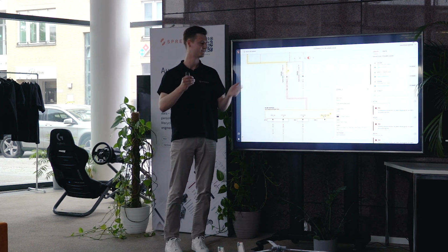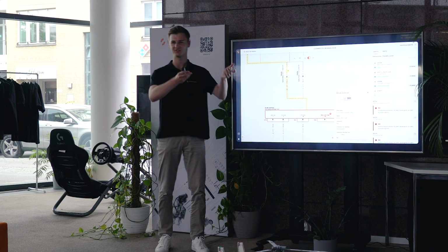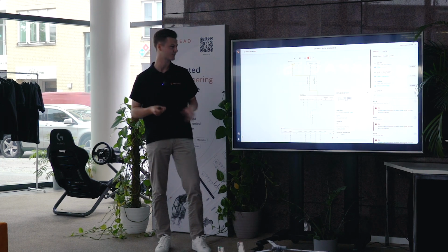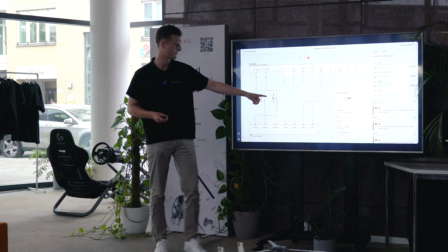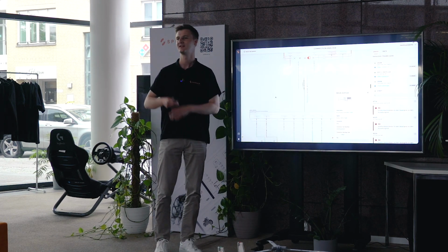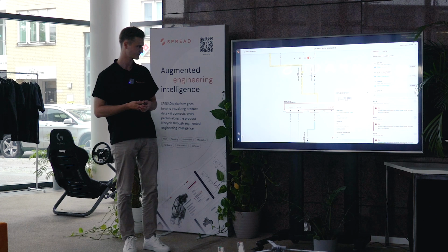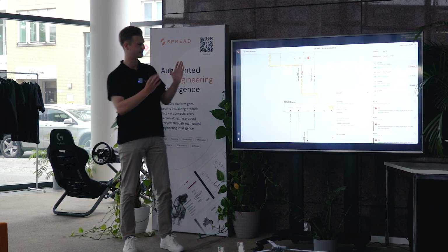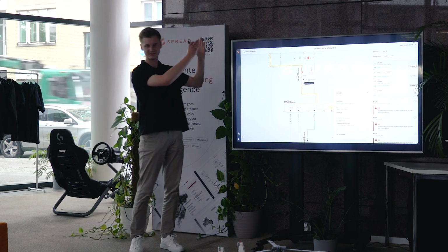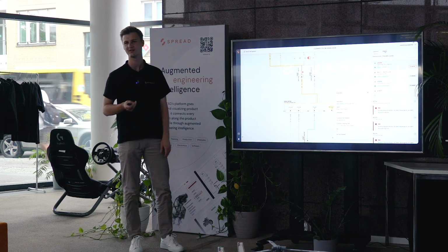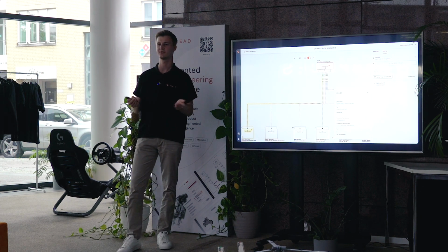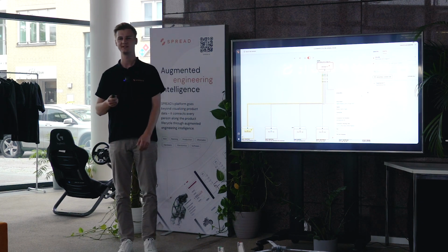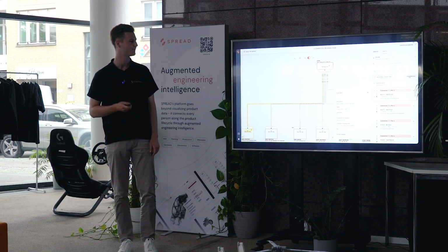We just add the information from the engineering department and from the production department and put it next to each other. We also add information about wires, colors, length, and cross-sections. And as you can see, we reduce the solution space to one specific path, similar to the path that Robert has shown, and just give the view that is necessary to really troubleshoot this specific error.